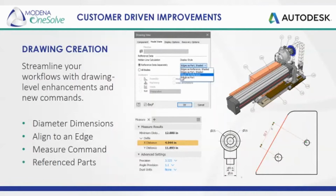A new set of drawing tools and functions have been bundled into Inventor 2021. This includes a new dimension type called parallel diameter. What this does is create a dimension with a diameter symbol when you select the outline edge of a cylindrical feature, such as a hole or a shaft.